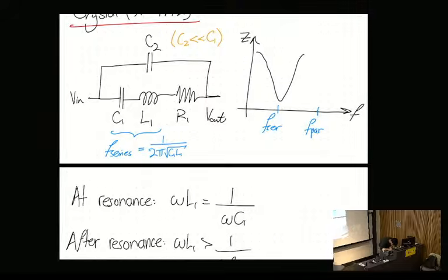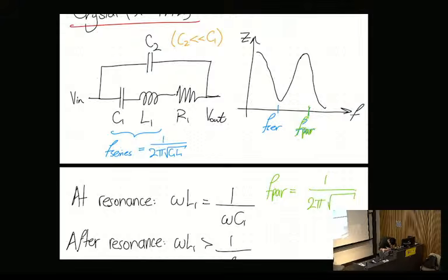Now this resonance, let's move this over, looks something like this, and then it decreases. Trying to draw it more selective. Okay, whatever, that'll do. We get the point. So you effectively go between a series resonance and a parallel resonance, and that parallel resonance has the formula F parallel equals 1 on 2 pi square root of L C2, right? So it's dictated by those two components.